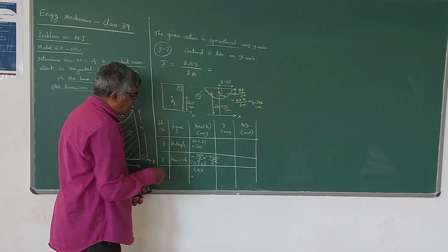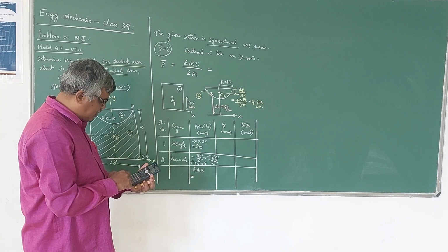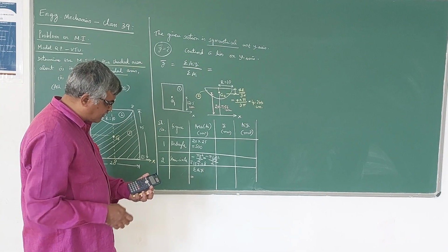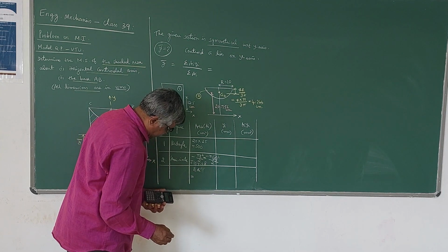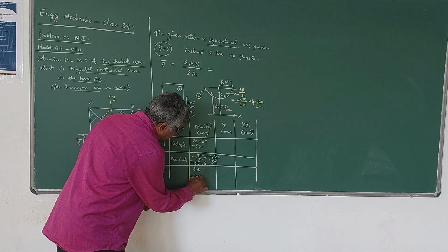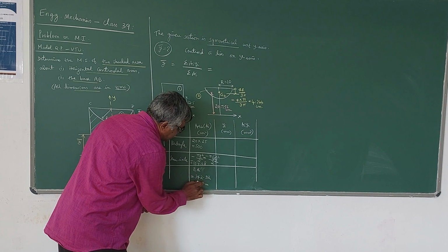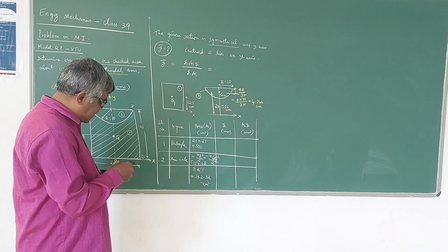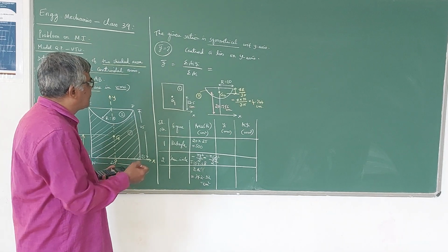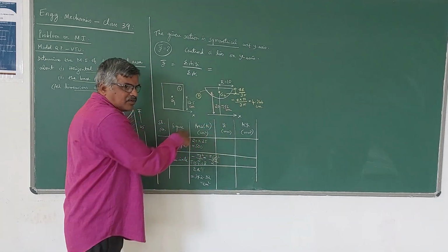Add this here, you have to subtract here, so 500 minus 157.08 gives the value of sigma Ai, which is nothing but 342.92 centimeter square. That is the area A. Then the distances of these two centroids, G1 and G2, from the x-axis, we have to write here. They are the values of yi.